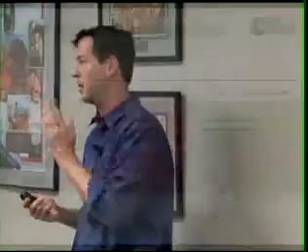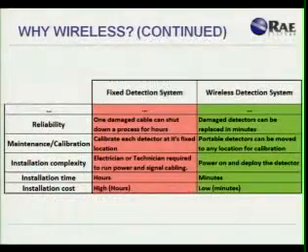And then finally, we're going to talk a little bit more about the costs in a few slides. But when you're talking about installation with a wireless system, you can literally do it in minutes. And when you're talking about a fixed detection system, at the minimum, it's hours, and most likely a few days to install a fixed gas detection system.